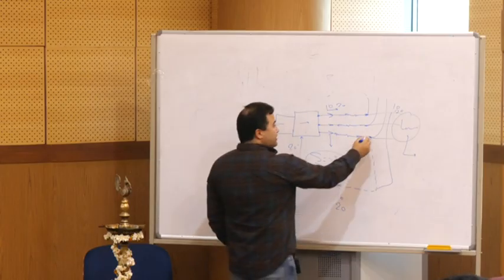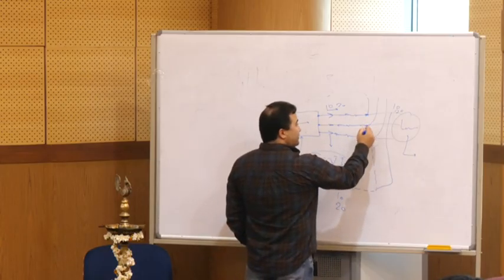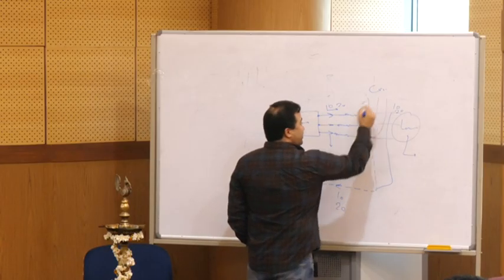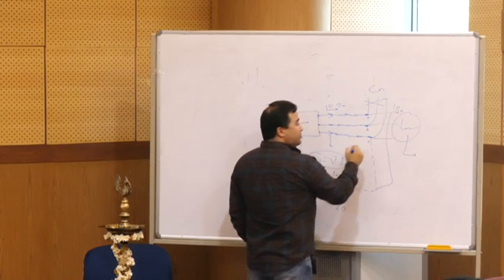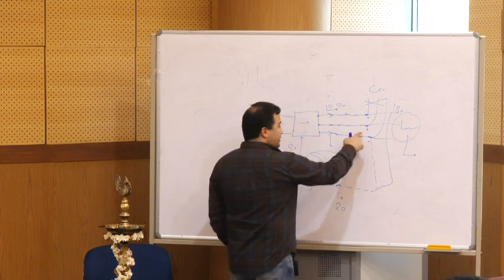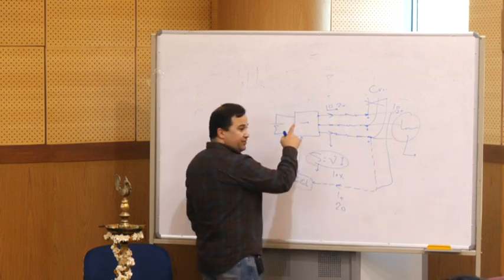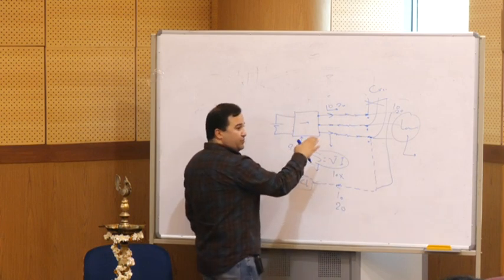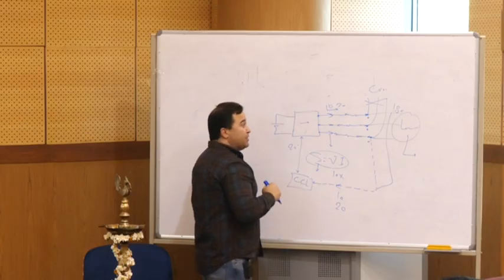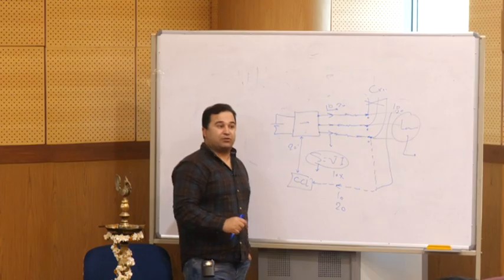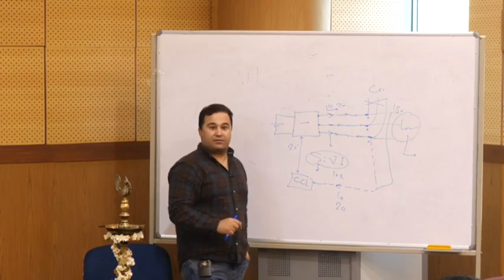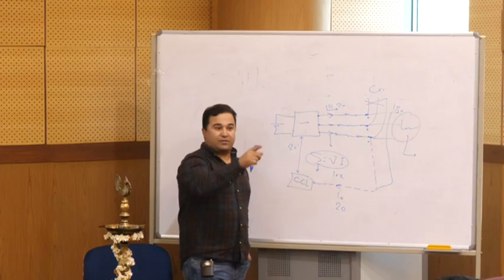And the controller is getting its reference from this voltage of the grid. But when an outage happens in the grid, the voltage goes to 0. So then it doesn't provide a reference for that one. So you cannot provide it, and it shuts down. So for this case, we use the PLL. Does anybody know what the PLL is? What is the phase lock loop?